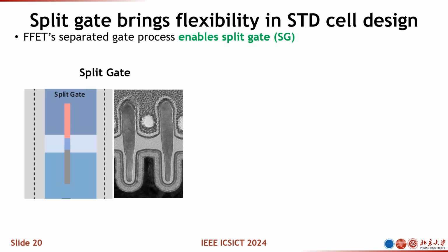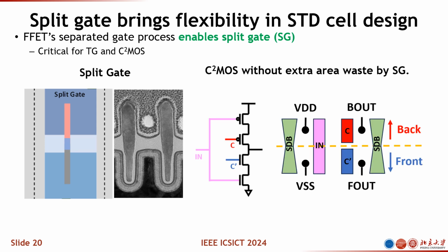The reason behind this actually is the sequential logic. Here I will show the clocked CMOS structure, the layout, and also the circuit diagram. You can see for the clocked CMOS, you have an inverter in the middle, and the input signals for this inverter are complementary. You would have a clock being injected into the gate of the PFET, and you have the clock bar being connected to the gate of the NFET.